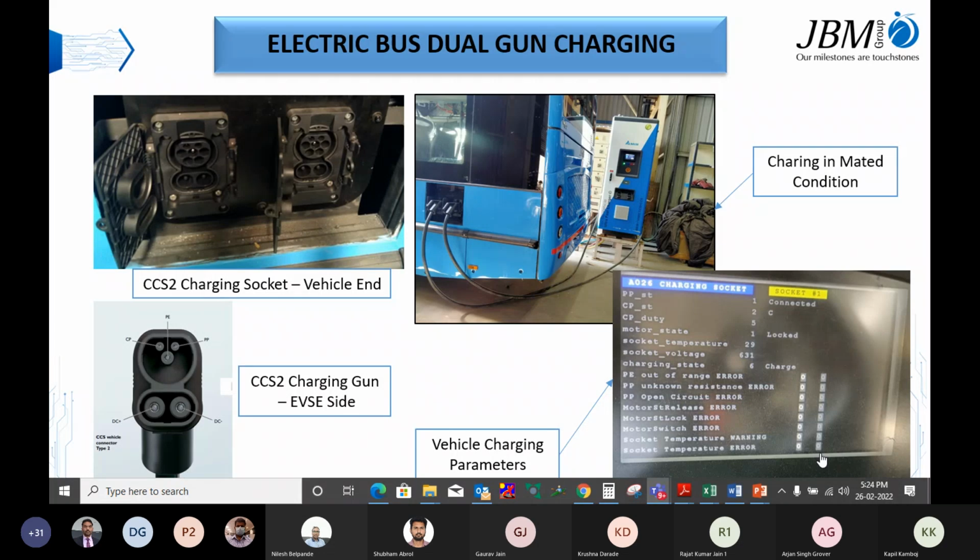Okay, and after 700, does it start decreasing the voltage, or does it remain at the same voltage? During the cable check, it will increase the voltage up to the required voltage, like 400 or 700 as per the charger. After the cable check, it will go back to 0 volt before the pre-charge state, because it has to build the pre-charge voltage. So it builds from 0 volt. Okay, got it. Thank you for the clarification.